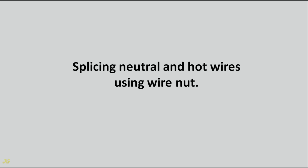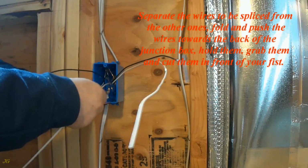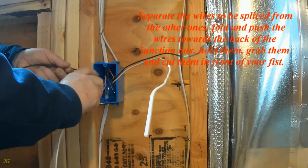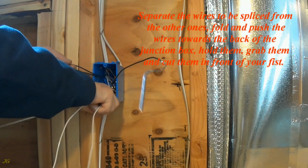Splicing neutral and hot wires using wire nut. Separate the wires to be spliced from the other ones. Fold and push the wires towards the back of the junction box. Hold them, grab them and cut them in front of your fist.